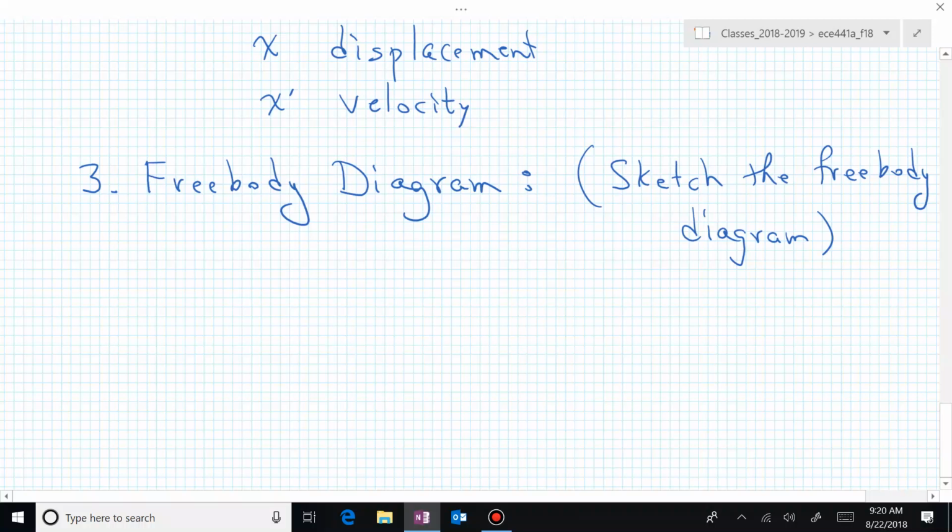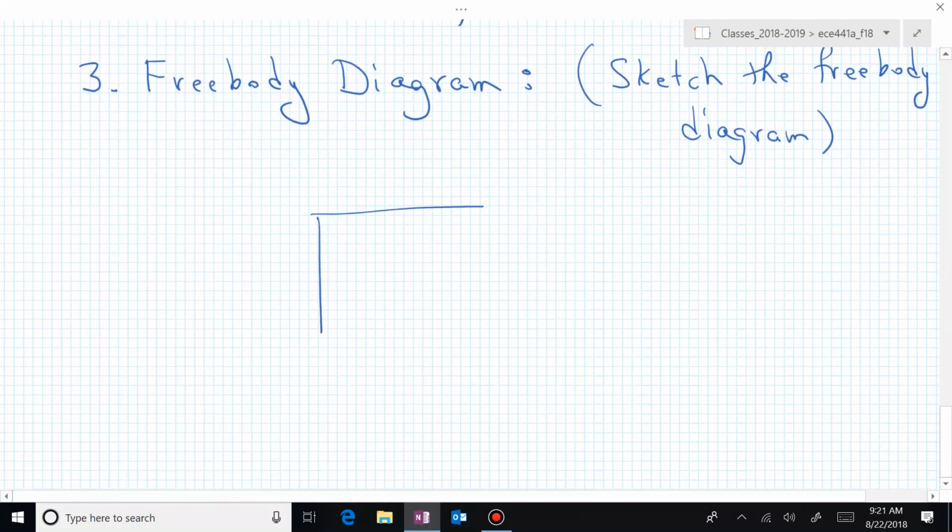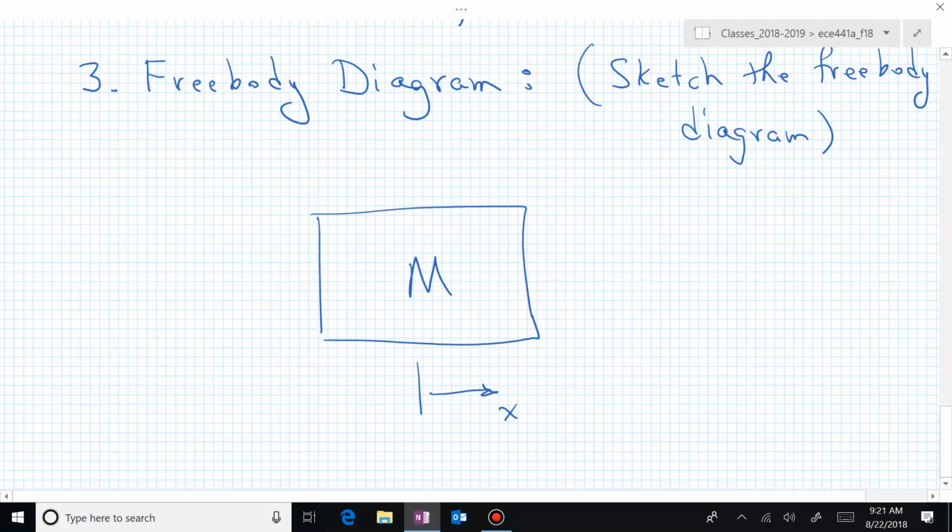If those points can move independently of everything else if you fixed all the masses. Here's a strategy that I'm going to discuss for this system, and try to do it in general, but it's maybe a little bit hard to think about when I just have the one mass. But if I had multiple masses, to find the free body diagram for this one, I would fix all the other masses and say, let me just focus on one mass at a time.